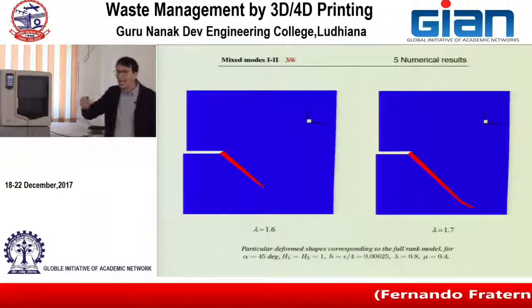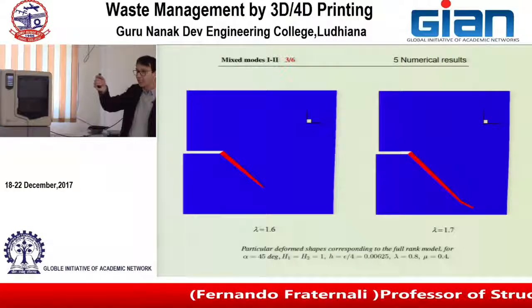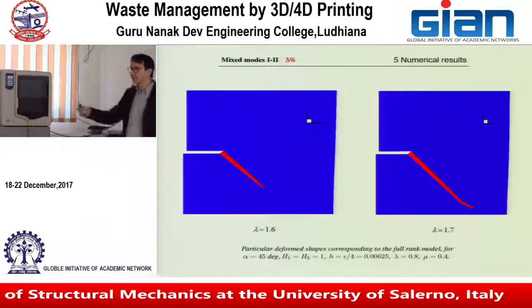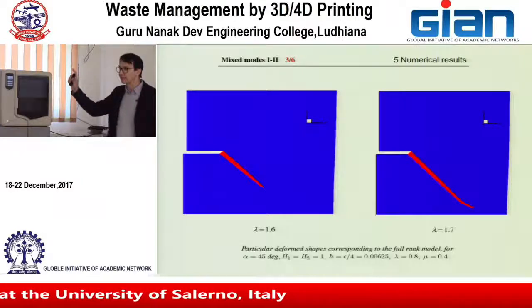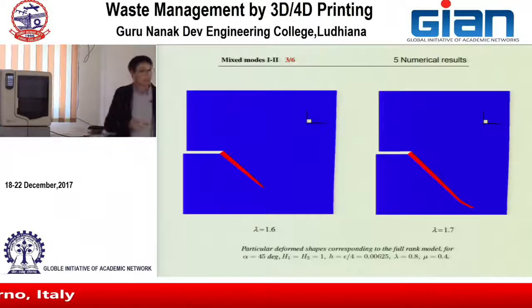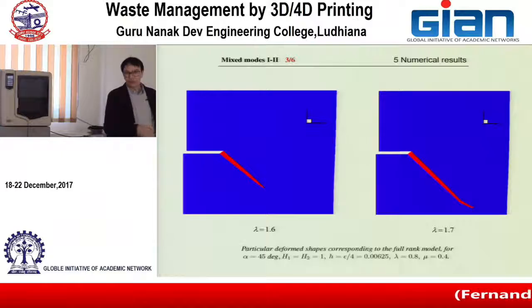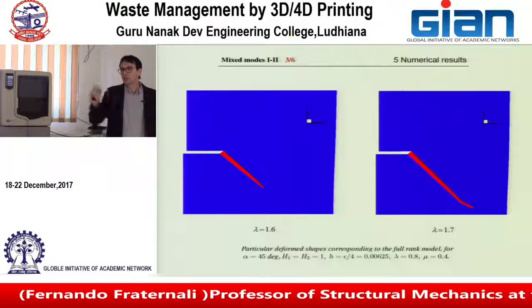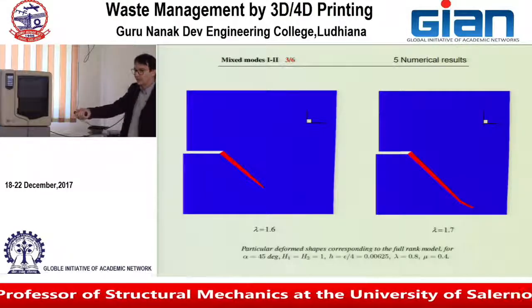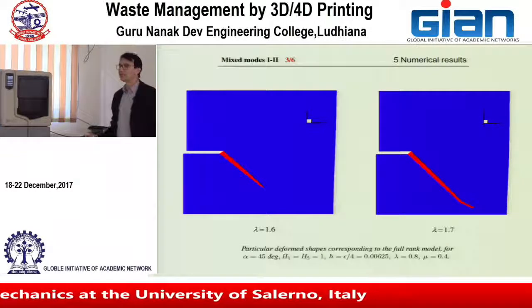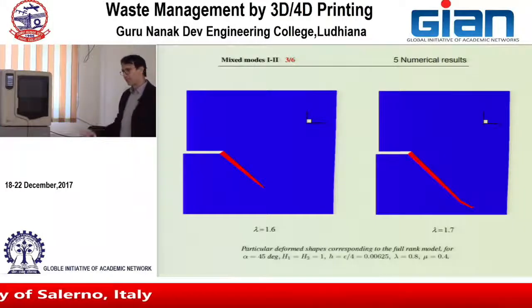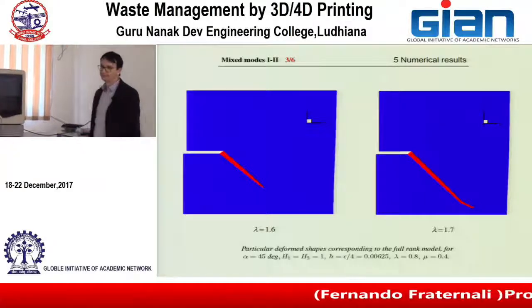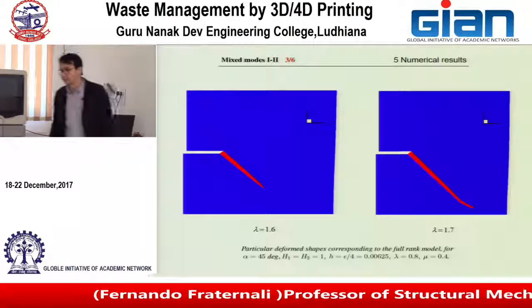So the area, in this case, of all elements that are at distance epsilon from the center of the element that you want to kill, where epsilon is a parameter. Then you divide this by 2 epsilon and you multiply by h, and you compare this increase of the energy with the decrease of energy due to the cancellation of the element. If this balance is positive or equal to 0, you cancel that element. Otherwise, you don't cancel.